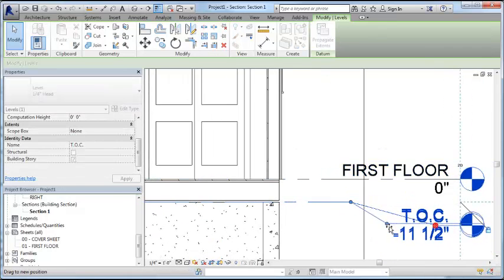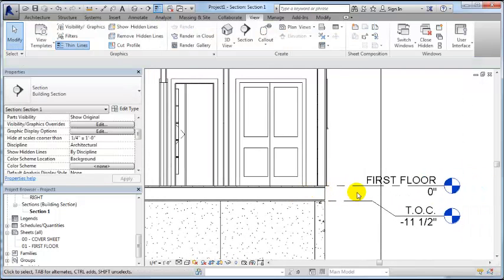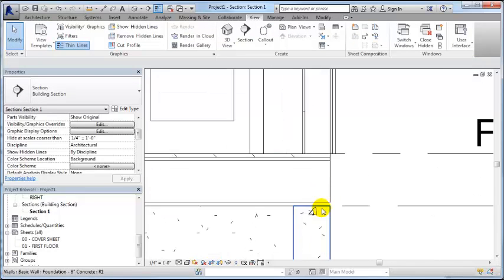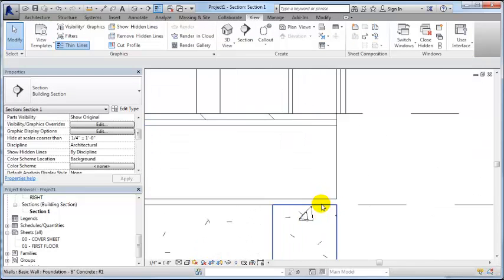One of the problems that we have here, I'm just realizing, is that our subfloor isn't matching where we want our subfloor to be with our floors. Also, we have only about a 3/4 inch gap here where we're supposed to be able to fit a 2x6 mud sill.